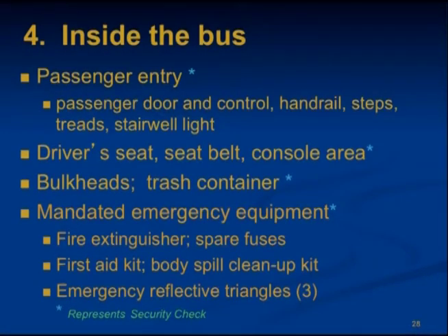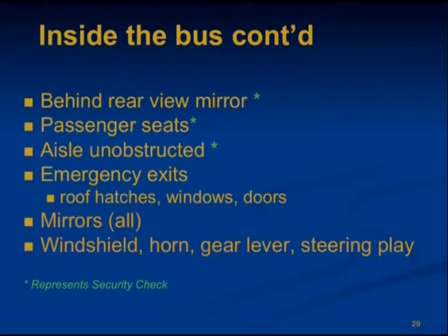Your first aid kit and body fluid spill kit are fully stocked and secured to the bus. Make sure you have your 3 emergency reflective triangles all present and the box is secured to the bus, and make sure that you have spare fuses if not equipped with circuit breakers. Continuing inside the bus, check above and behind the interior passenger rear view mirror.